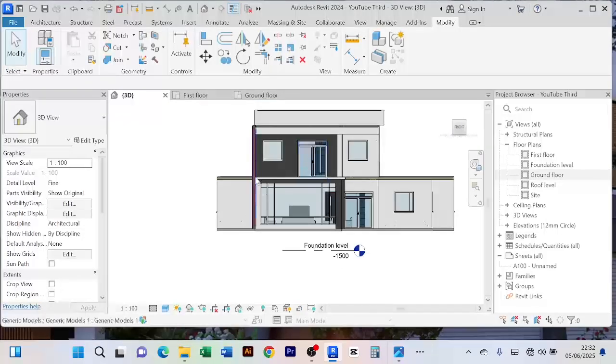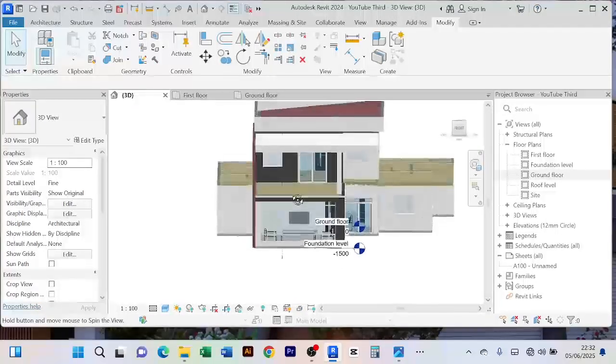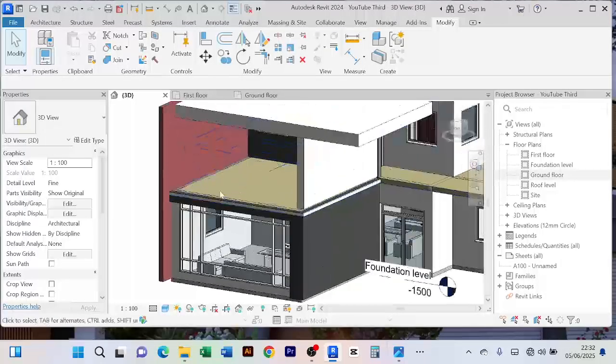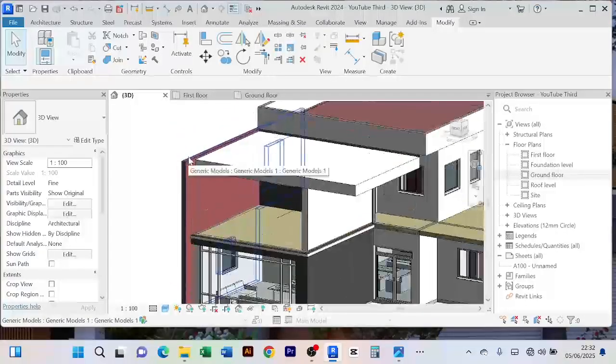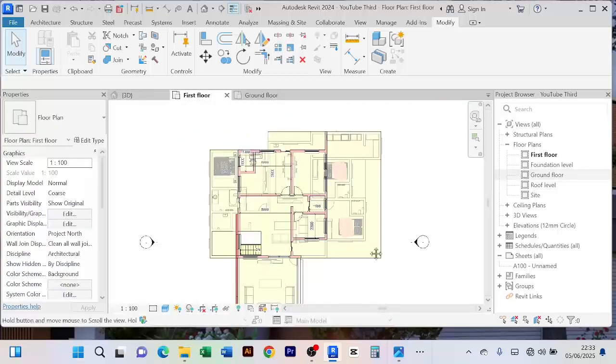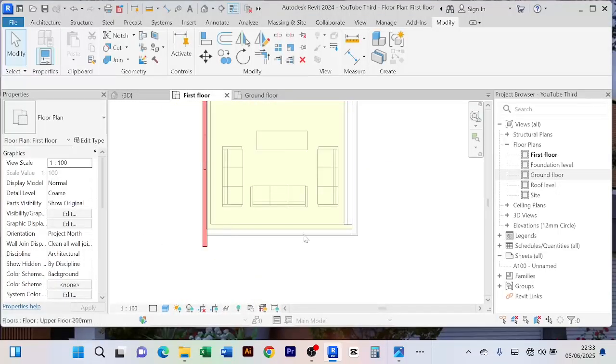And then of course this upper part here, I want this side to be covered with railings. Now you're also going to see how you can create the railings, or how you can place railings. So for you to create the railings, you come to the floor plan. This is an upper side, so we come to our first floor. So we're going to create the railings here.